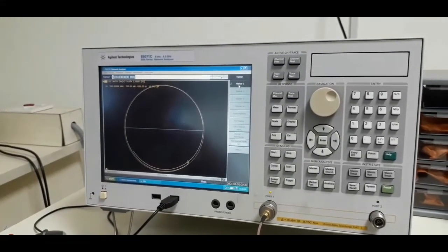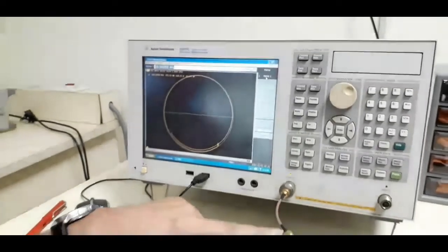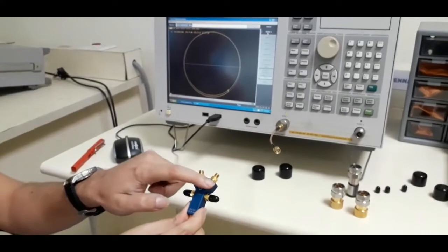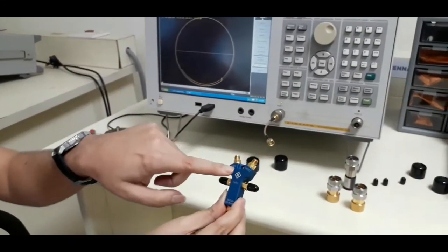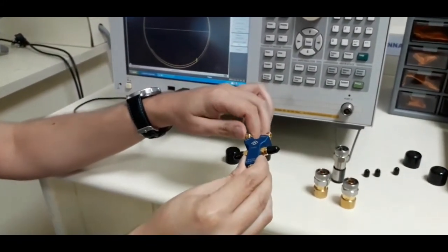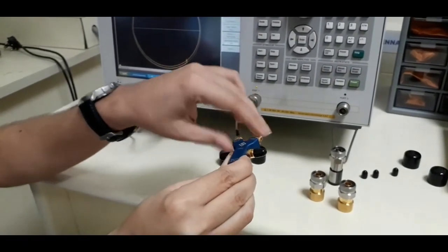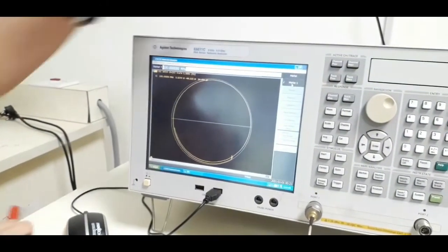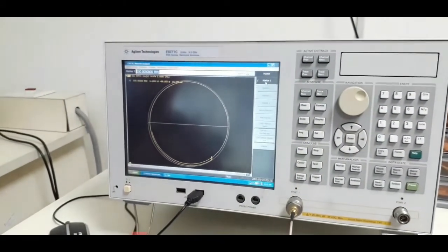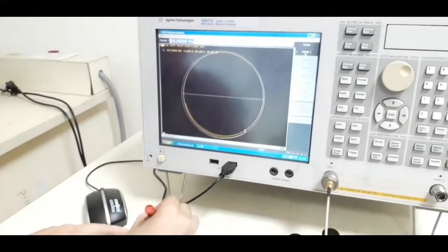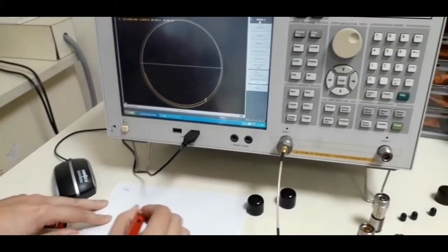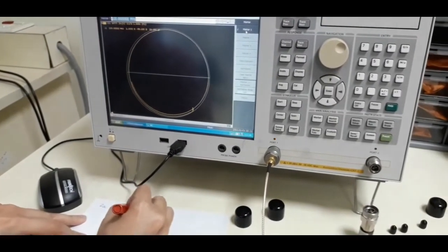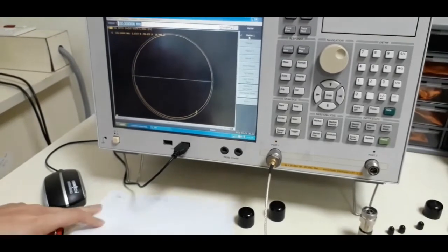So the first step let us do is to measure the characteristic impedance of this transmission line. To do that, I am going to have to terminate this transmission line using first an open load followed by a short load. So you can see this is open. Let me connect it over here. You would not expect much of a change. So let us note down this reading as ZOC. ZOC at 100 megahertz is 1.1 minus j 99 ohms.